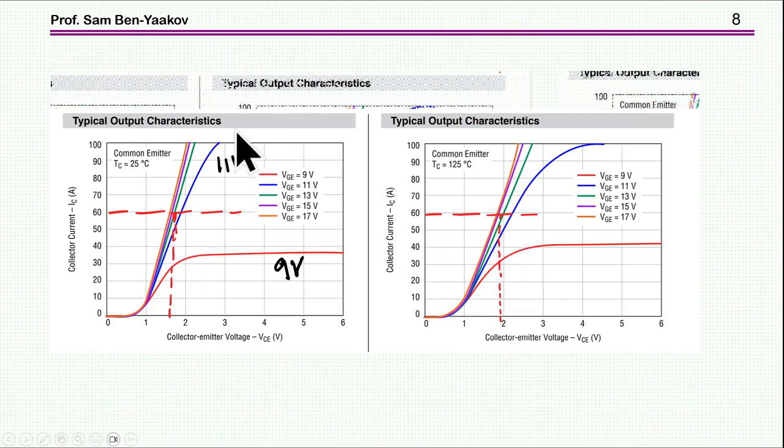Okay, saturation level is much higher than that, and you don't want to go that high. So in fact, in many cases, although you call it DSAT, you are really not entering the saturation region, but you just rely on the fact that the higher the current, the higher is the collector voltage, and therefore you can detect it and then disconnect the gate or lower the voltage of the gate.